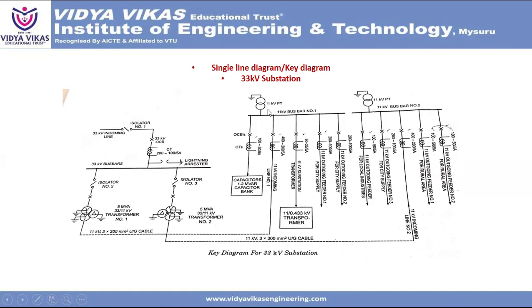Potential transformer is always connected in parallel. So that's why the primary has one terminal connected to the bus bar and another connected to ground. Okay. From the 11 kV bus bar, they give outgoing feeders, that is feeder number 1 for consumers, feeder number 2 for local industries. From the other side of the bus bar, 11 kV bus bar number 2, there is outgoing feeder number 3, and this is the incoming feeder for rural area 1 and then rural area 2.